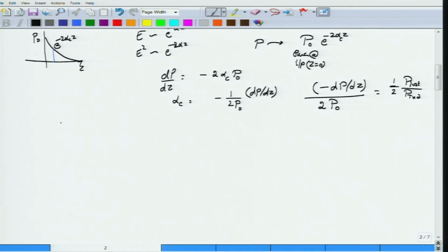So consider the expression for the power loss for the skin depth. From the skin depth analysis we already know that the power lost per unit area is half Rs into H mod square, where H is the magnetic field, and this is the H that we need to evaluate on the surface.